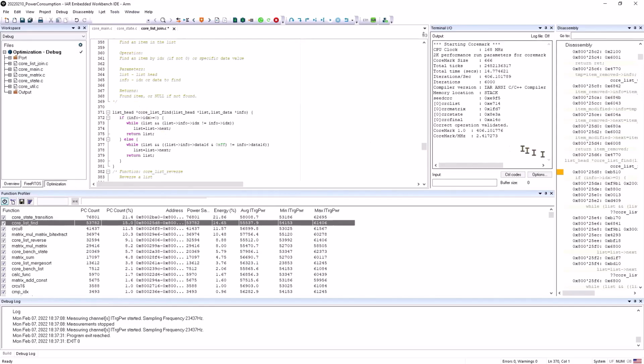And then you could use this increased performance either to set the MCU into sleep for a certain amount of time, to check how long this sleep period can be until you still have the required performance and what is the effect on the power consumption. Or you could give it a try to reduce the clock frequency of the MCU.